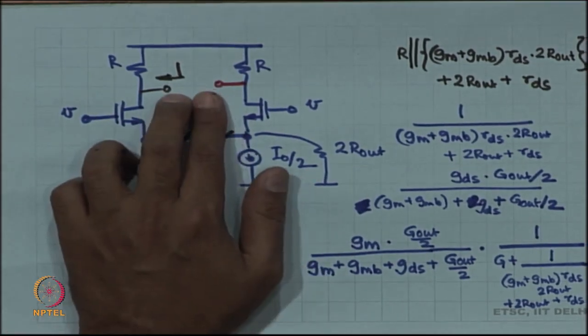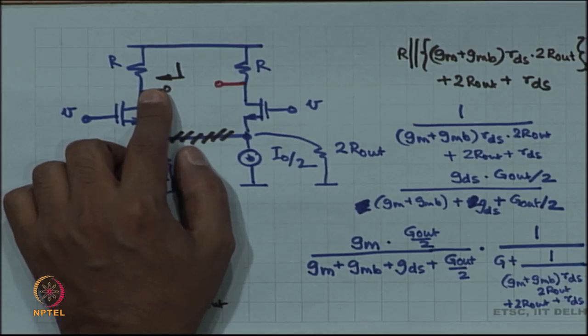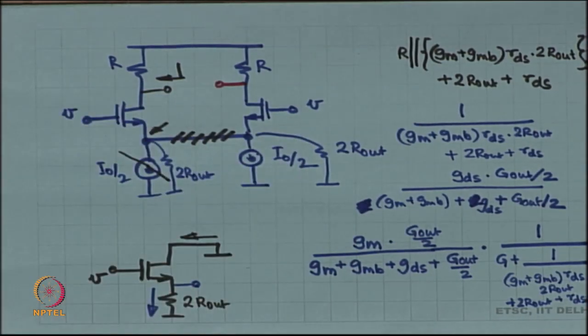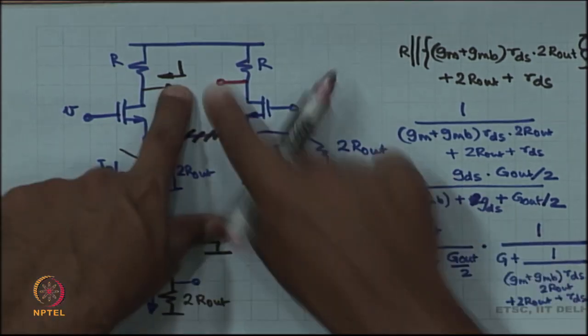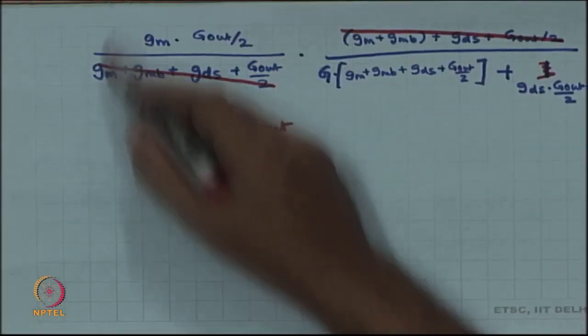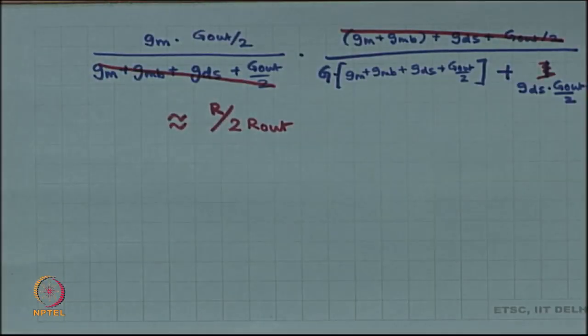The average of the two is going to be just one of them because they are equal, and the average of these two inputs is just V. So, average by average is equal to just this, fine. So, that is your common mode gain when we are saying average of outputs by average of inputs, common mode of output by common mode of input.